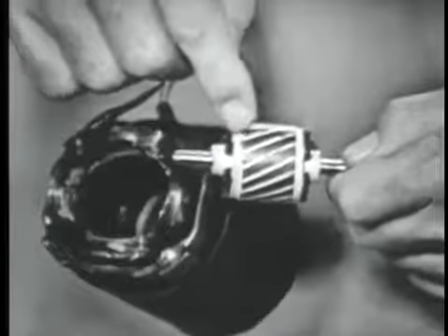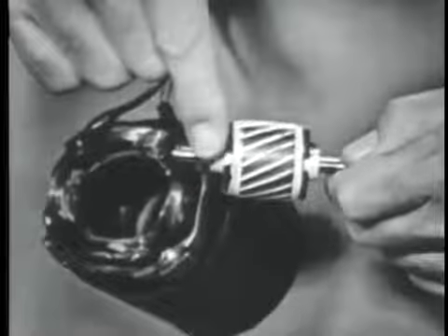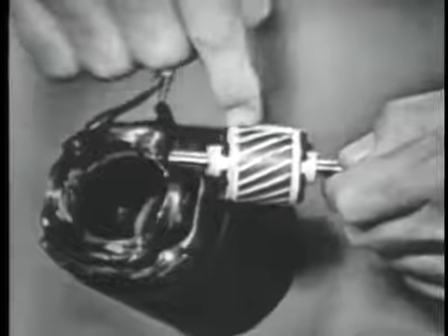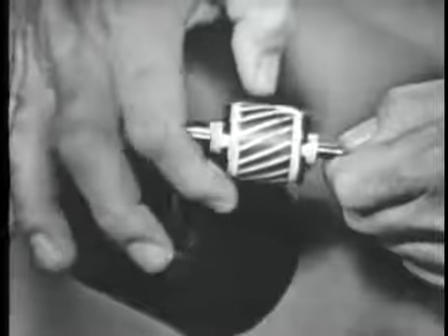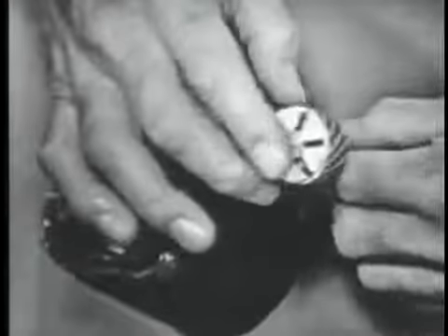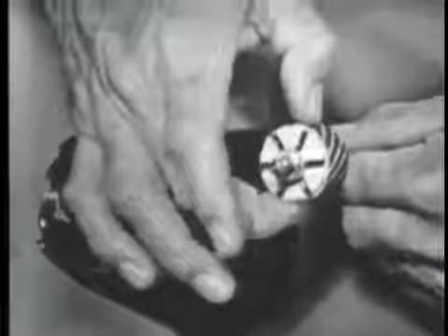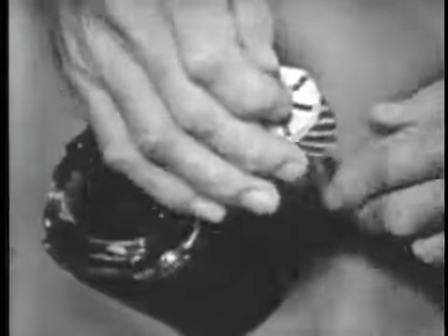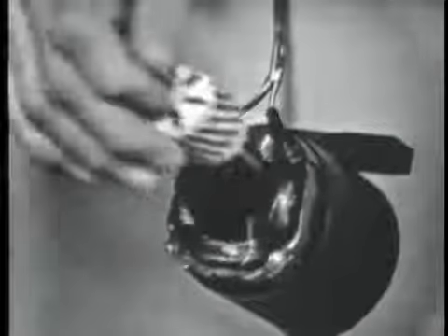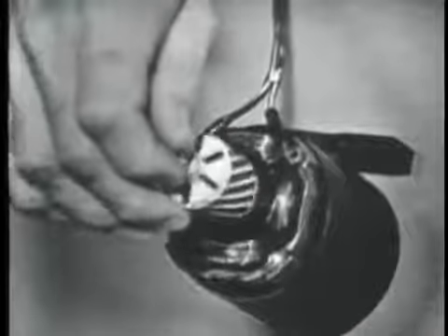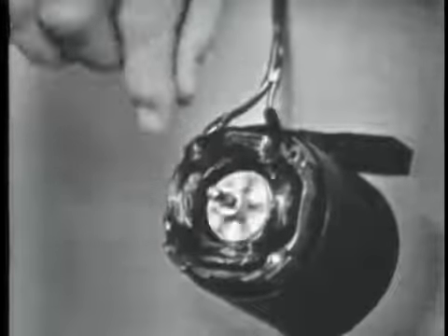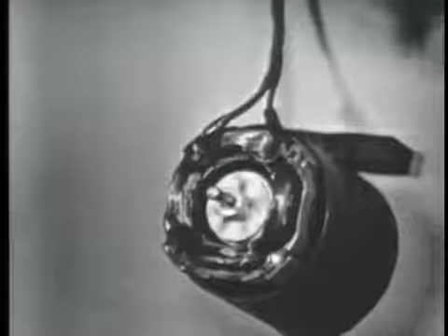Now, as the rotating field goes around this rotor, current is caused to flow in the rotor, which sets up a magnetic field, and the rotor develops a north and a south pole. Now, once we magnetize the rotor, it has got to follow the rotating magnetic field, as you've already seen, just like that. Okay? That's it. The rotor follows the rotating magnetic field as soon as it becomes an electromagnet.